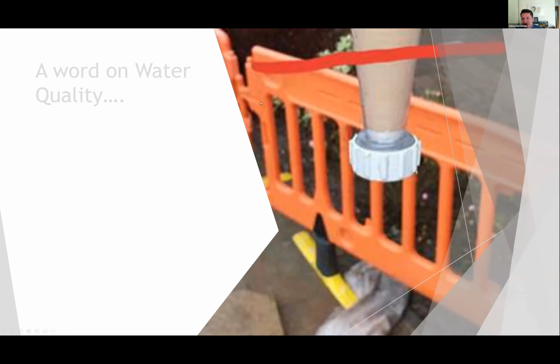This rather poor picture, I'm afraid, here is a cone that is used to work out how much particulates are in water. And I'll deal with particulates first. So there's three types of water quality concerns that we generally have with open loop systems. So particulates: if you've got a water well that's generating sands, for example, or any other particulates, then it's really a well development issue. And John talked about well development last week in a bit of detail. So that's how, once the drilling operation's finished, that well is then put to use.